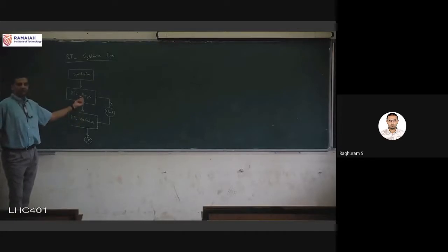Okay, so we have added this one step here, which is your RTL verification. And this is traditionally done using your test bench. That is, you are writing some Verilog code and you write another file called a test bench. And in that test bench, you instantiate this design and you give it different inputs in random order or any order you want, but that particular step is called RTL verification. And once this is done, and you're sure it is correct, now we go for the